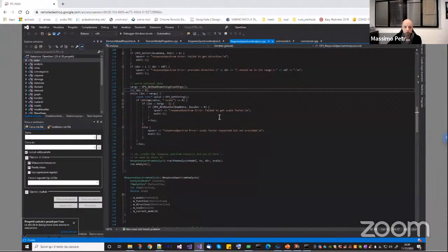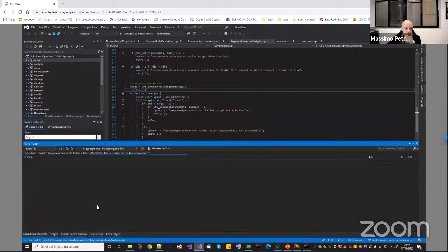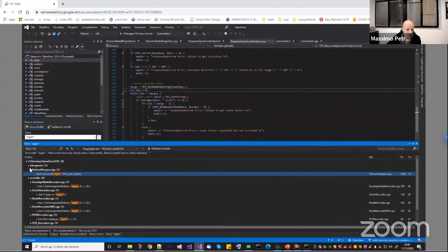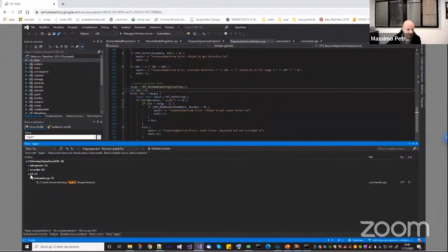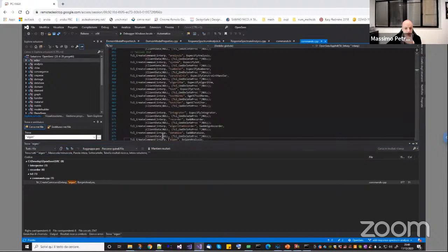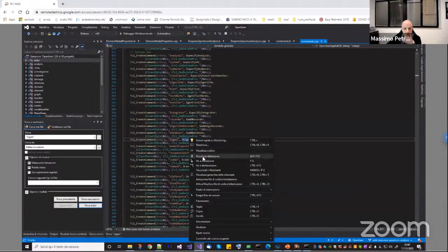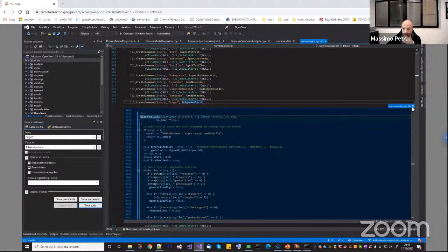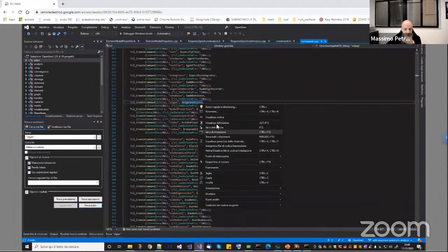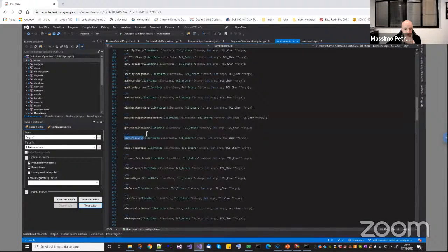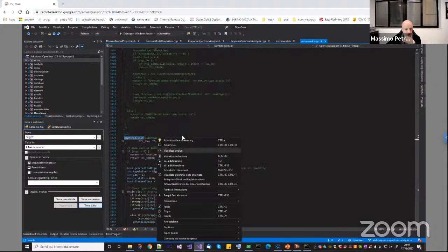So if you don't know how to navigate inside OpenSees and you want to find the eigen command, you can just type here eigen, like this, and then search all. You will find many of them. If you're using OpenSees STKO, you need to go under the TCL report, and then you go here. Here you have the eigen command, and when they find the eigen command, they run the eigen analysis. You go here, in the source code, and then you go here.